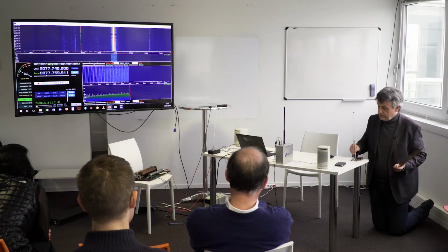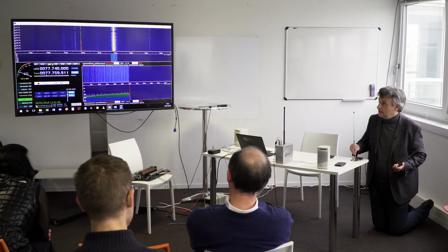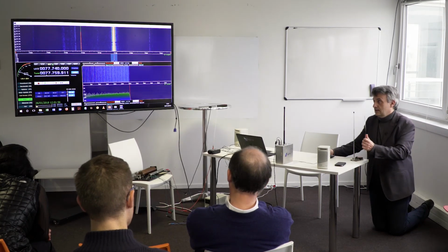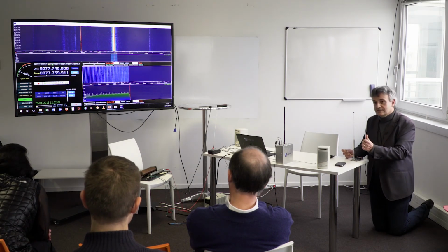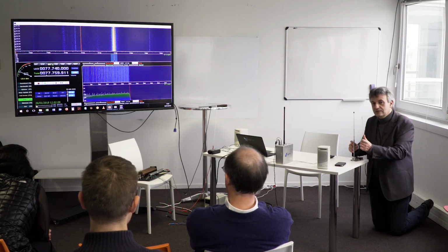So I might have a well-tuned antenna. Okay. If I'm changing the environment, I might have some trouble. Maybe I can retune it a little bit. Maybe I miss one extra component. Probably I miss a cap here in parallel to retune the system. So it's difficult to retune it optimally.